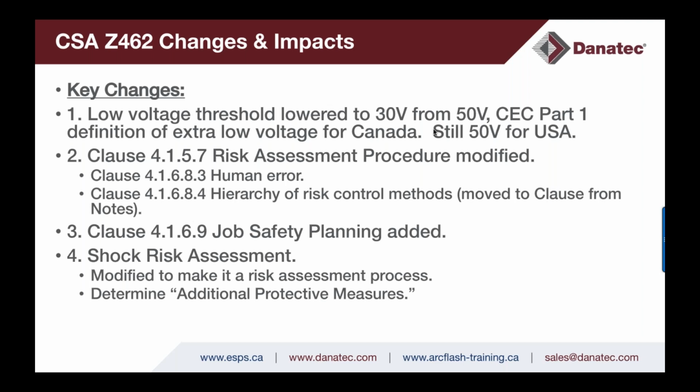Again, I think that is another valuable addition: you should have job safety planning, which implies that you follow the workflow process flow chart. Then you want to identify the hazards. You want to make sure that arc flash and shock risk assessments are completed, with implementation of the controls. You want to make sure that process is planned out and then implemented by the worker in the field.